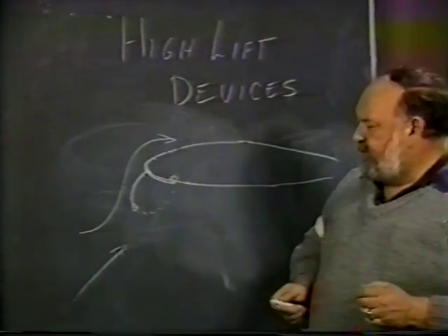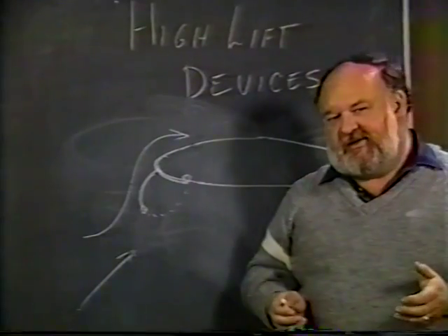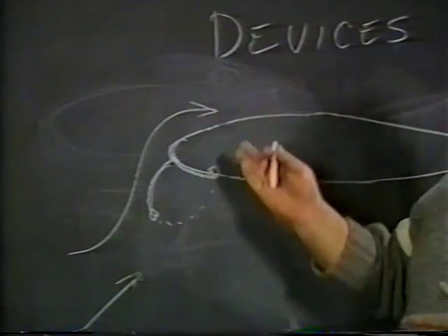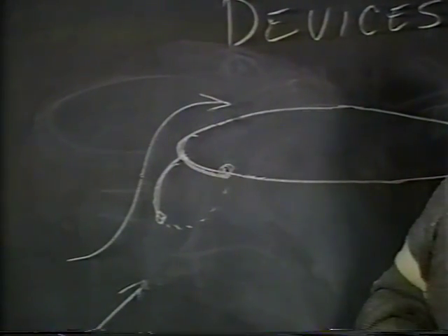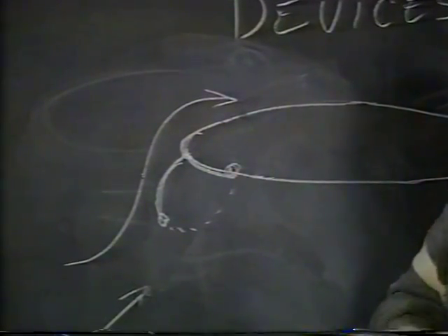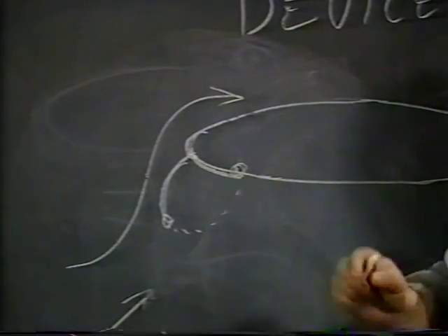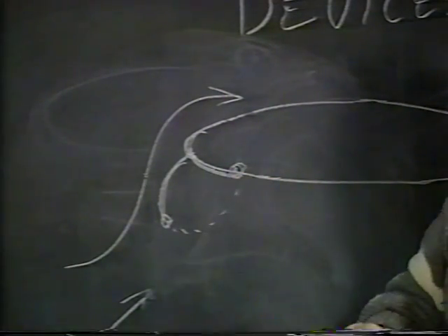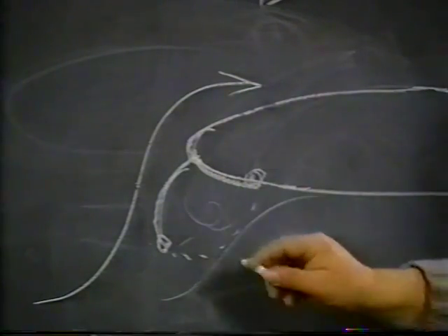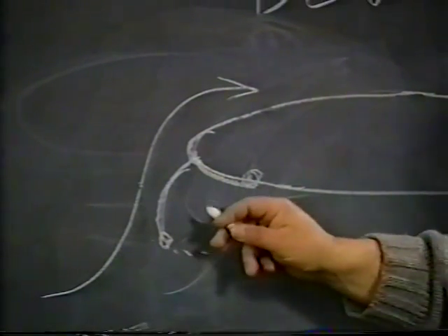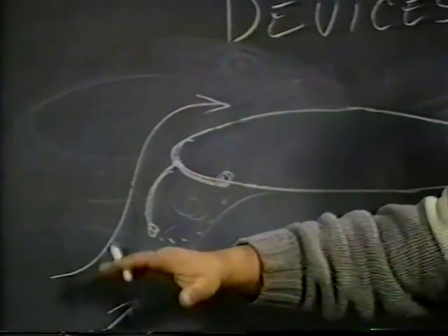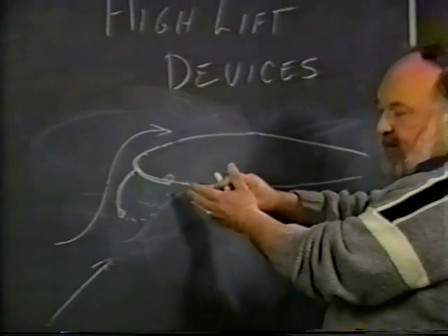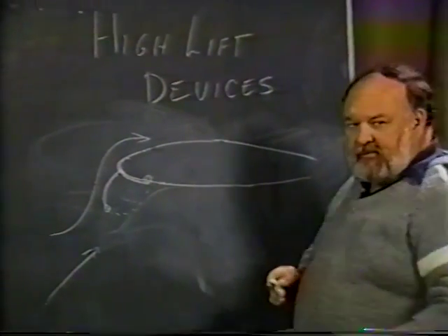You would not want to use a Krueger flap on an airfoil section that, say, is 12 or 14 or 15% thick, because really with any airfoil, your leading edge radius is already big enough. But when you're dealing with really high-speed airplanes where you must have a thin wing and you must have a relatively sharp leading edge, the Krueger flap can work reasonably effectively. The Krueger flap will have a flow separation right behind the leading edge in here, but as the flow comes on the bottom, this separation will not be bad, because it's actually going to be pushed right back up to the surface and flow along the bottom of the wing.